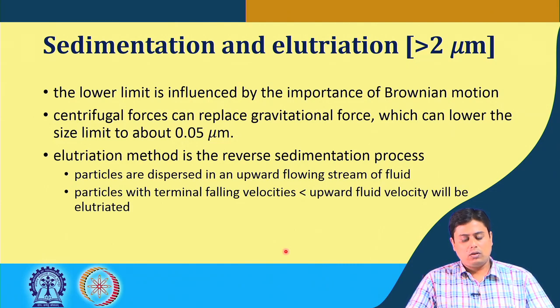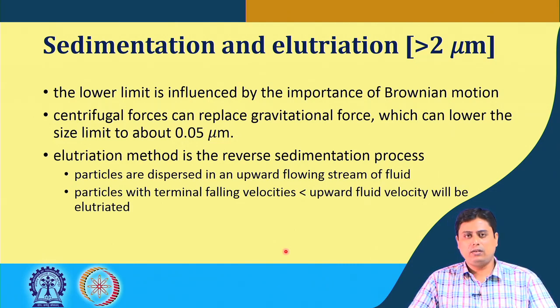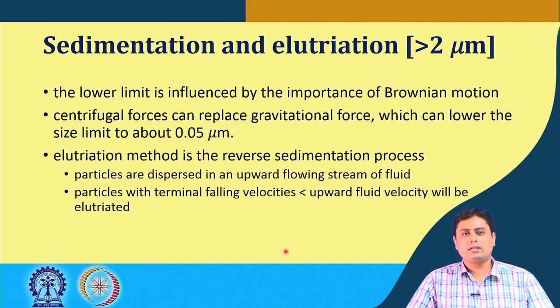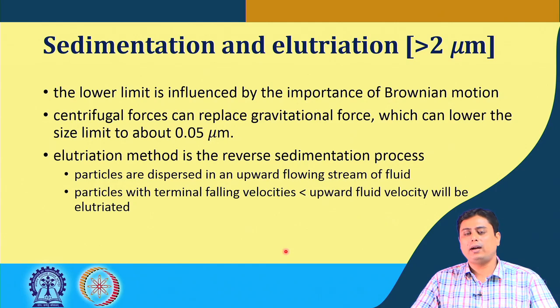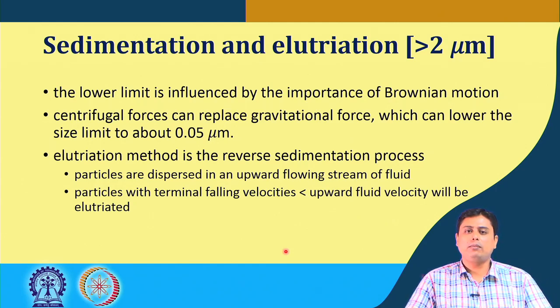Centrifugal force can replace this gravitational force. Instead of simple normal settling, we can introduce centrifugal forces in that domain to enhance the settling process, and in that case a size limit of about 0.05 micron particles can be settled, because you can understand that such lower size particles under normal settling conditions may not settle and can be suspended forever.